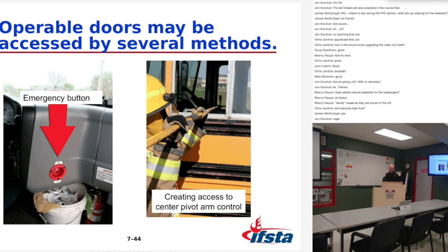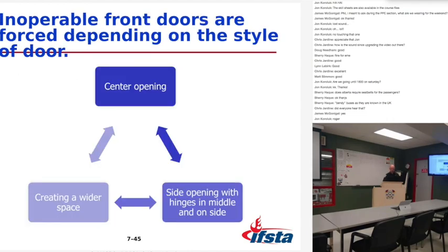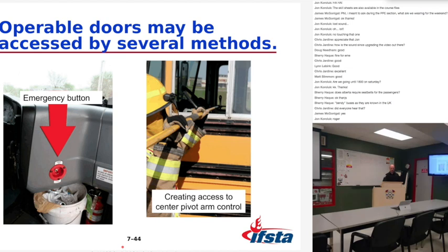So again, we can remove the windshield with that by pulling that gasket. Ways to open air actuated controls. Reach through the driver's side window and operate the main switch located to the left of the console. Use backup release in the stairwell inside of the door, then manually open.